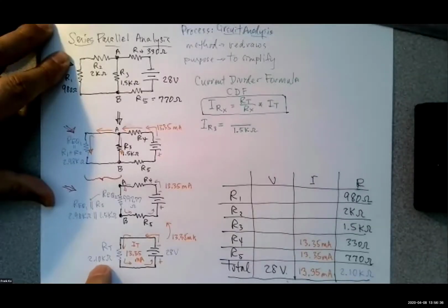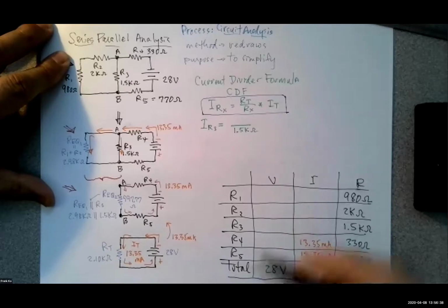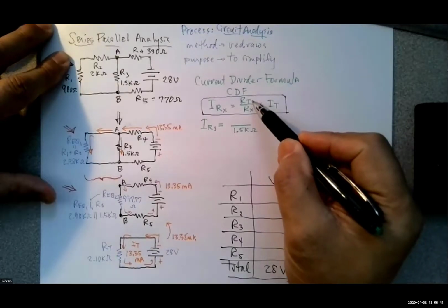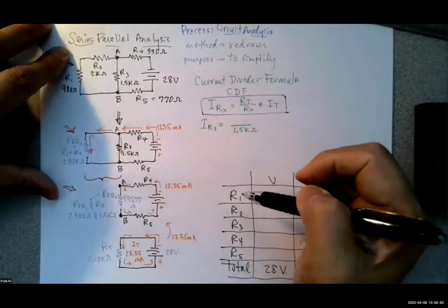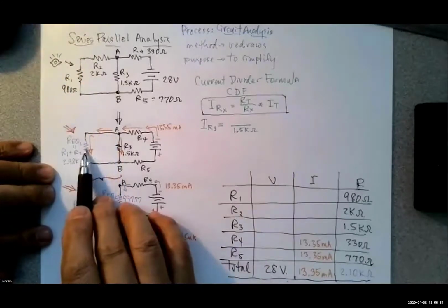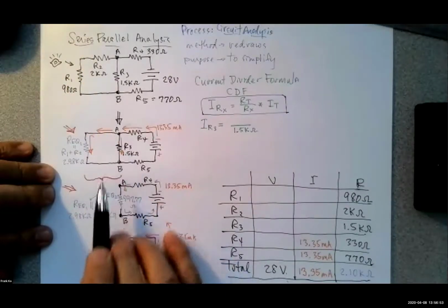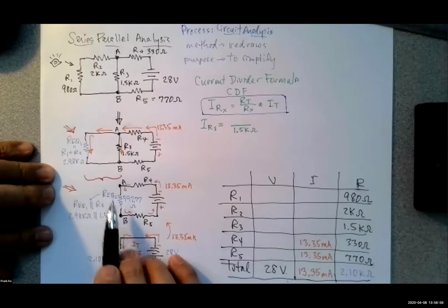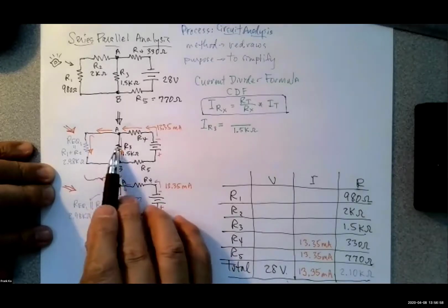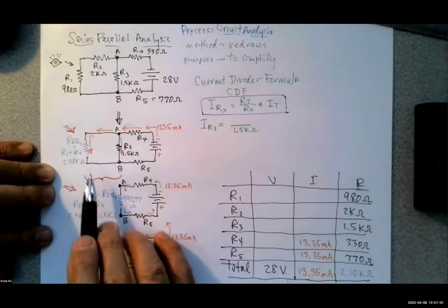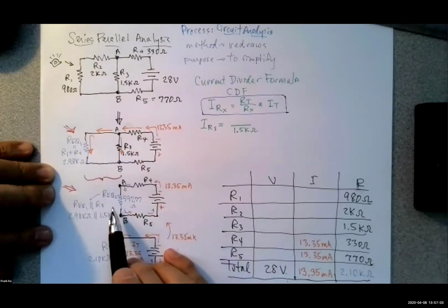No, that's not right. And Rebecca now realizes that can't be, because RT is for the entire circuit. So what do we actually use for RT in this formula? Oh, it's the 997.77 ohms. Precisely. These two combined in parallel gave us a total for the bank. The two resistors form a bank, which is the nickname for a parallel circuit. And the total for these two in parallel came out to something called REQ number 2, which was